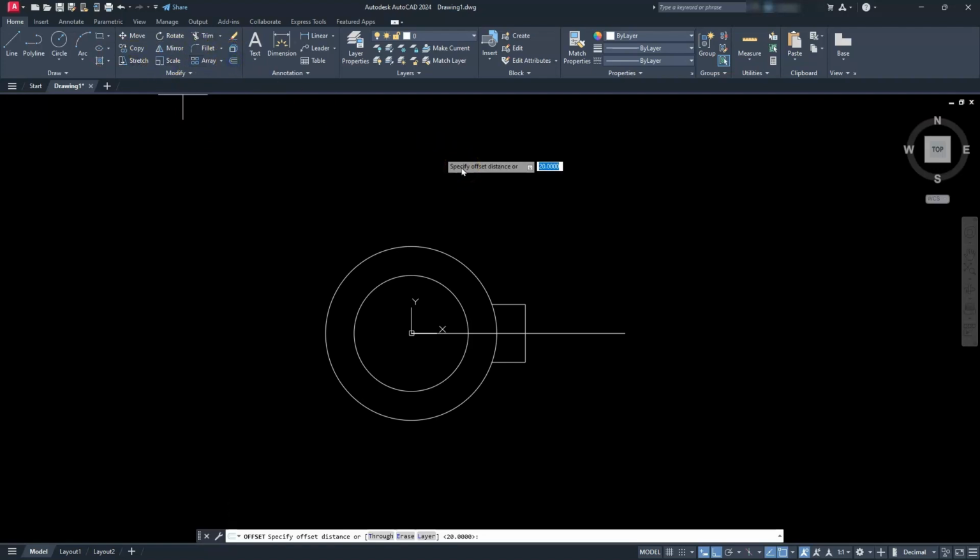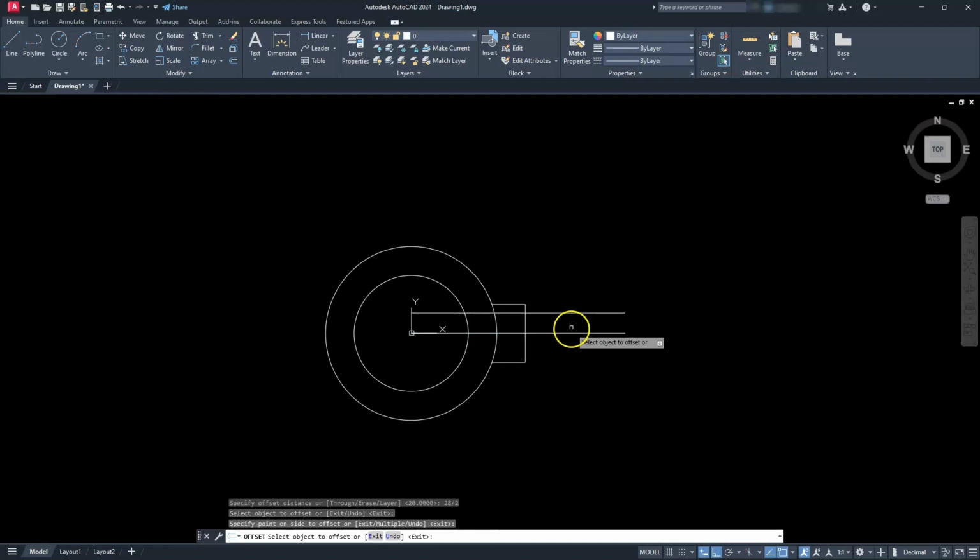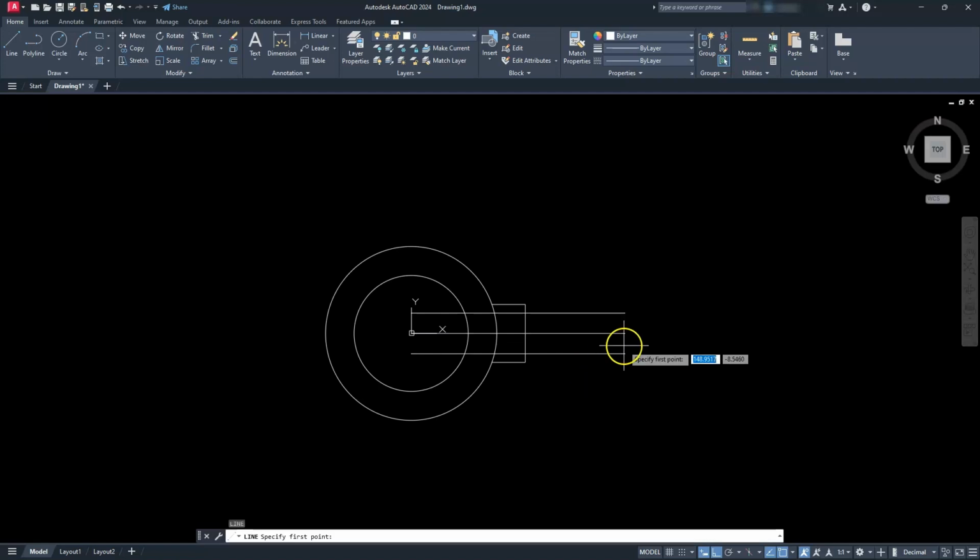And if you don't feel like doing the math and figuring out that that is 14, you can also type in 28 divided by 2 as the offset distance. As long as the numerator doesn't have any decimals, this works fine. And then let's go ahead and offset that. Go in that direction, and then this one going this direction, right? I'm going to draw a line going right across from that endpoint to connect here.